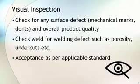Visual inspection is conducted on fittings to check any surface imperfection. Both fitting body and weld are checked for any visual defects such as dent, die marks, porosity, undercut, etc. Acceptance of these defects is as per the applicable material standard.